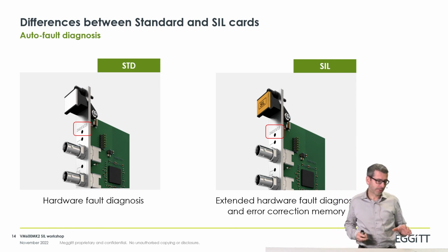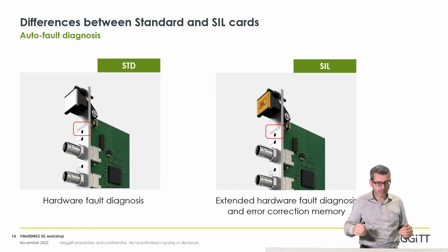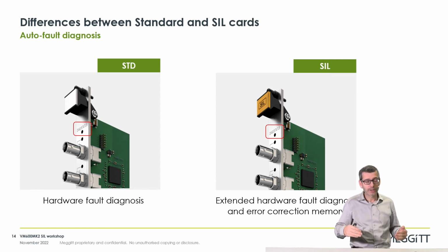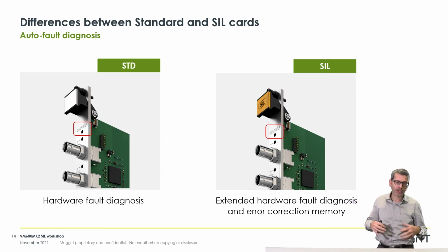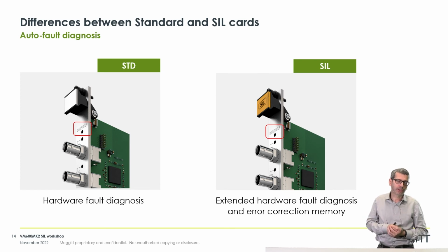There is another difference in terms of diagnosis. As I mentioned, the standard card is doing some diagnosis on the power up. That's why it takes a few minutes to power it up. Same applies to SIL. But then there are some additional tests that are run while the configuration is running. So they are all the time monitoring the health of the card itself. So it's important to note that in case of the SIL, the coverage of that auto-diagnosis of potential failures on the card has a larger coverage. So it is more comprehensive.